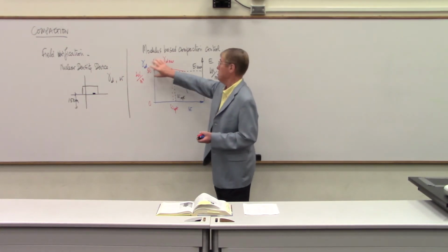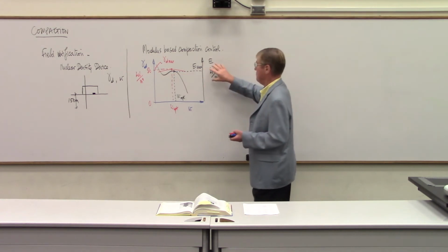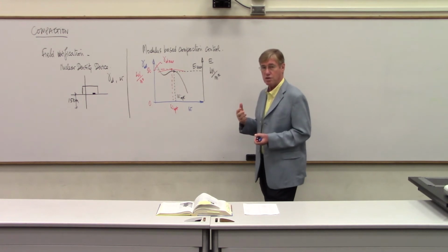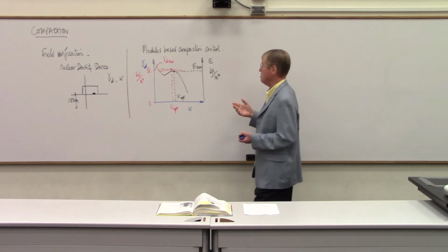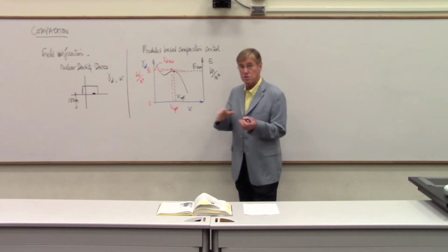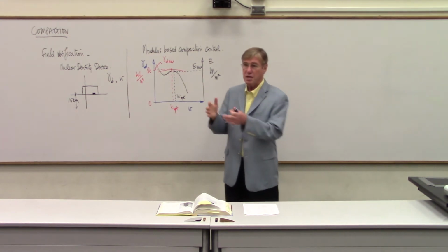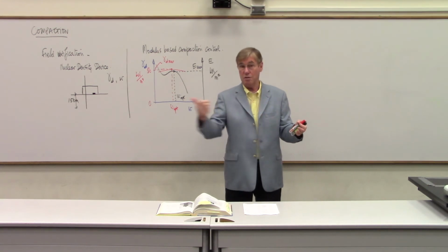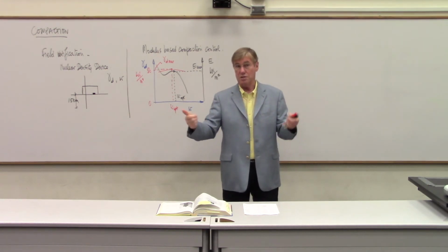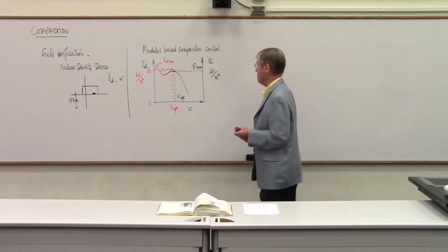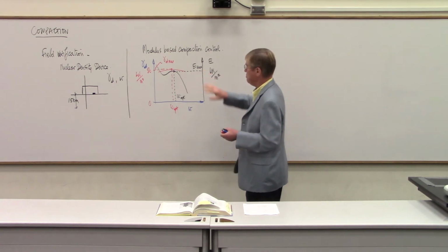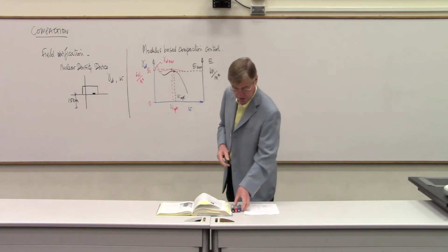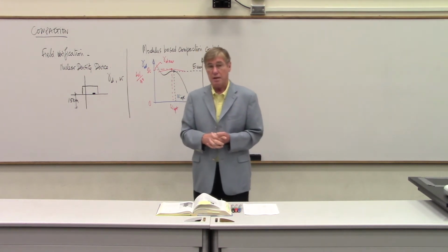So concentrate on this thing, but be aware of the fact that in my mind, it makes more sense to measure the modulus than the dry density, because the modulus is what we use in the calculation, so it makes sense that if we use a certain number, when we come to the field, we want to verify that the number we use in the calculation is going to be verified in the field. So this is the trend for the future. All right. So that concludes our discussion on the compaction.